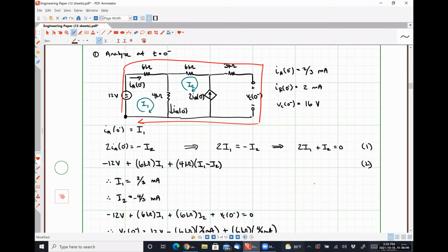Yes. So let me explain why I believe that nodal analysis would have been easier without solving for anything. If I had done nodal analysis here, and I'm going to do what I would have done in blue, I would have chosen this guy as my ground. I have a voltage VA here, and let's call it V1 and V2 here, just so that I'm not using alphanumeric subscripts.